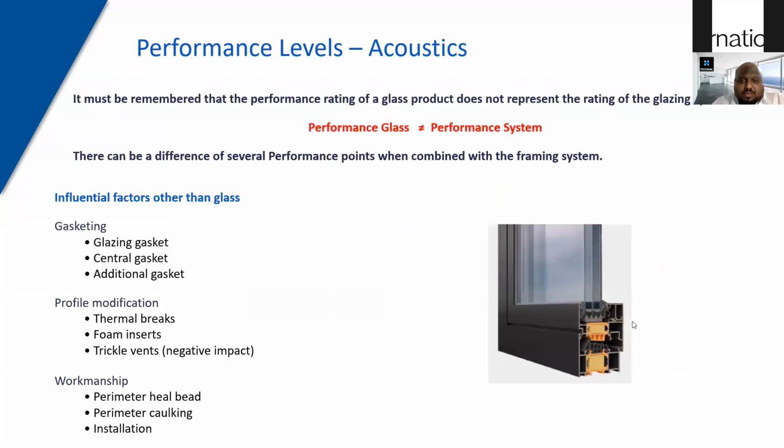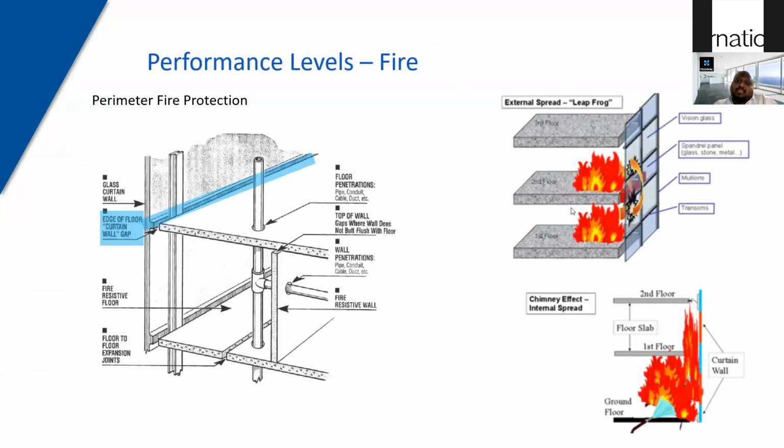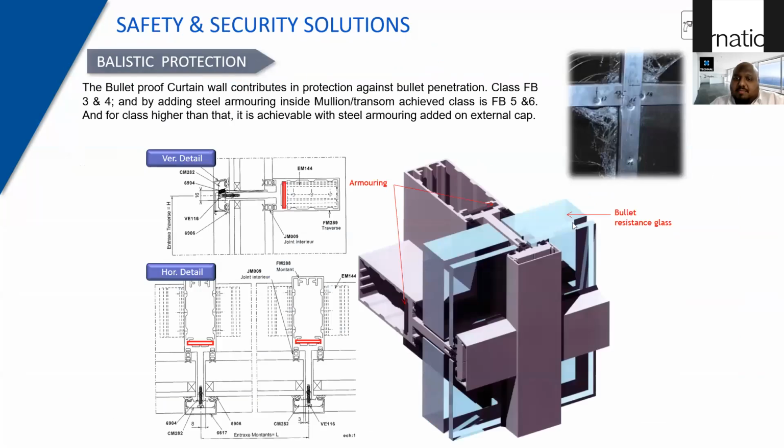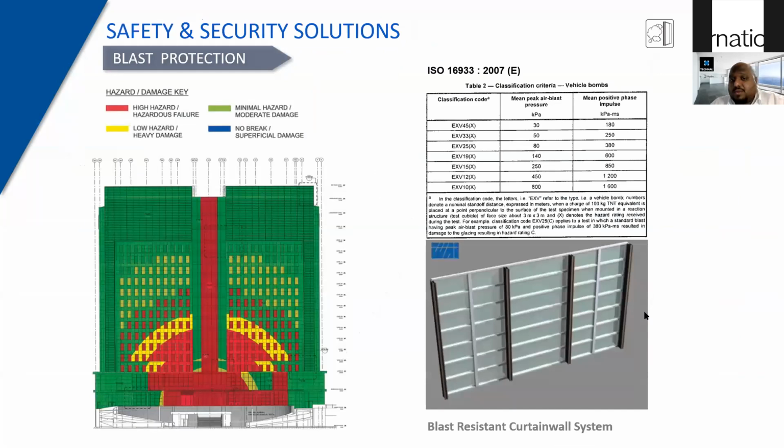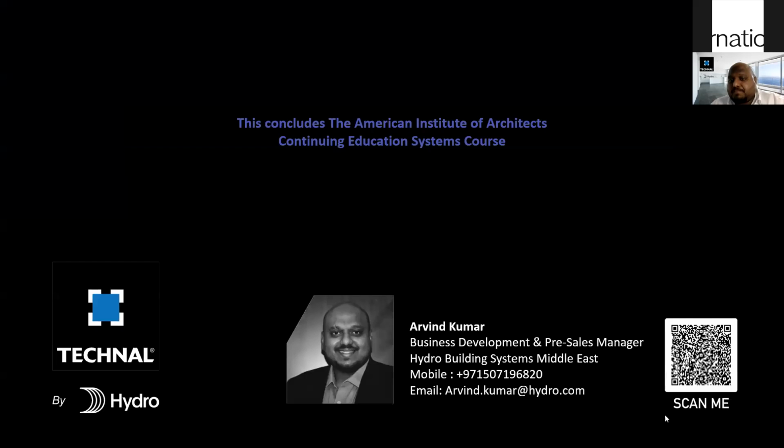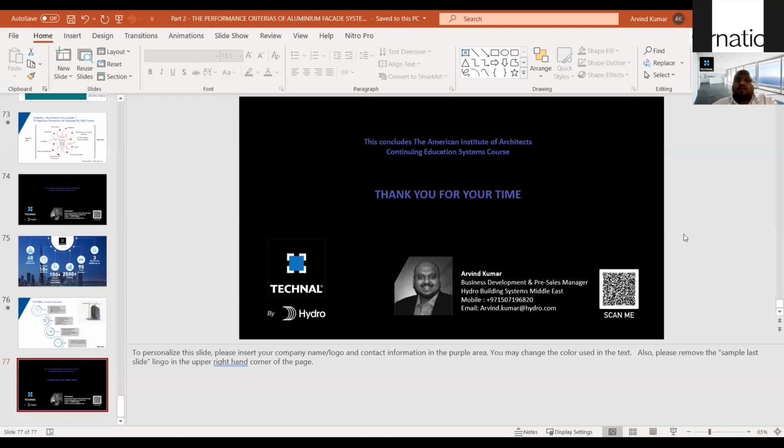This is a good example of our window system, where you have the outside frame and the inside frame, split by the polyamide profile, and in some cases we use additional PU foam to further reduce the conductivity from outside to inside. I hope this answers your question. This is how we make sure we use thermally broken frames on all our products.